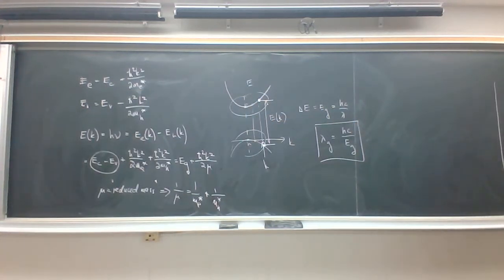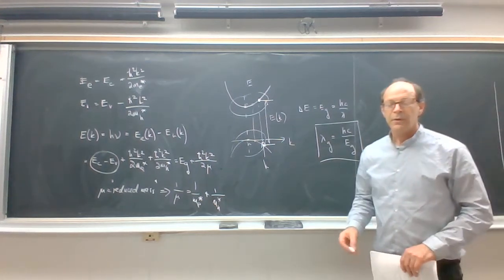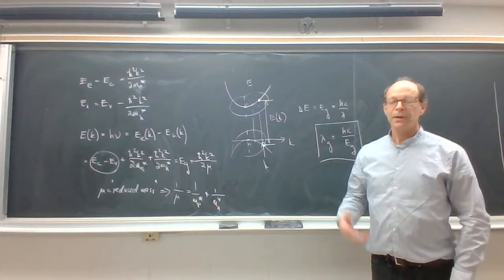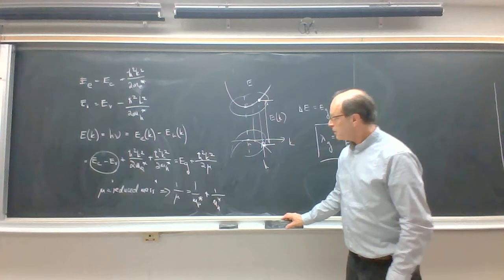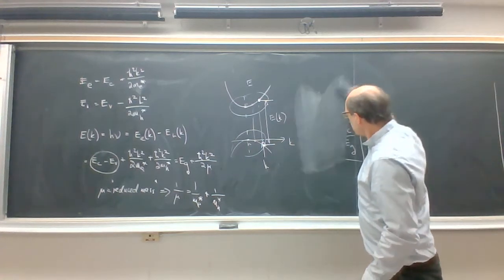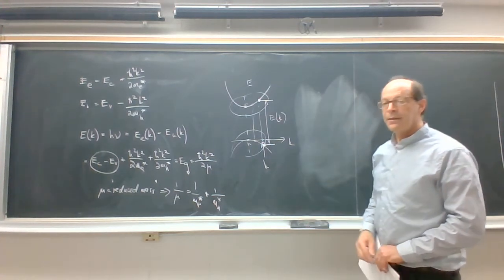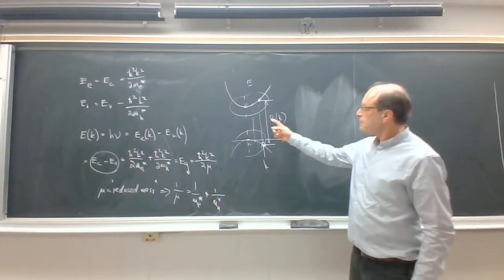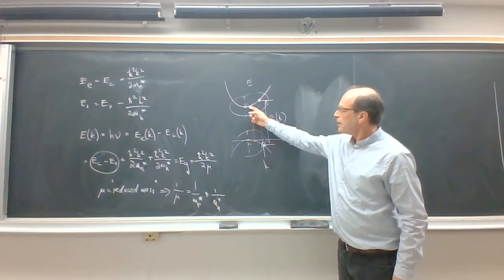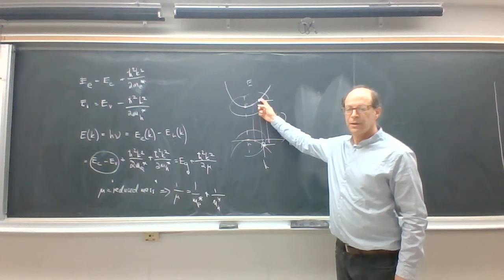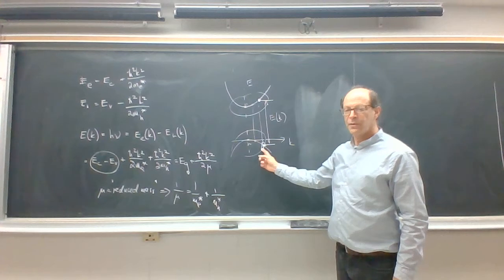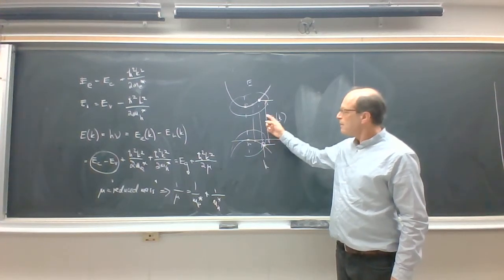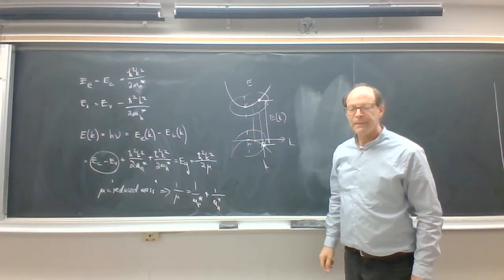So the issue now is how do we make sure that we get the correct spectrum of emission? The emission spectrum is going to depend on the electrons that occupy the states in the conduction band, and it's also going to depend on the availability of holes in the valence band to accept the electrons that recombine.